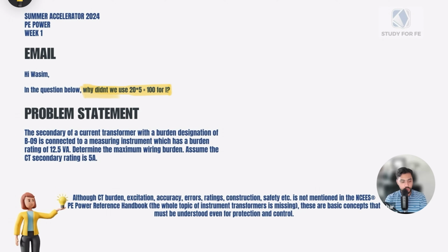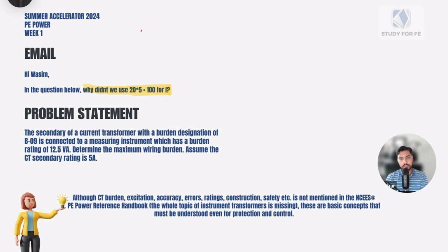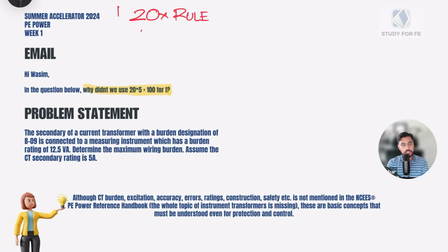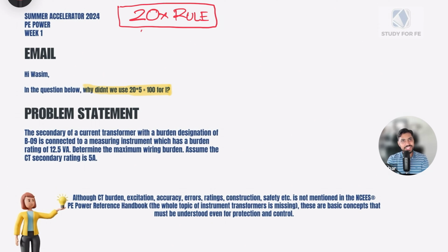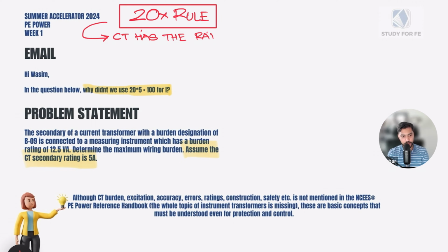Now this 20x rule, those of you who have gone through the on-demand content and the live training recording as well, when I went through that, I told you guys that we need to be a little bit careful with using the 20x rule blindly. Because in reality, and I'm just talking in general terms right now, this 20x rule really applies to scenarios where the CT has the rated burden connected, correct?